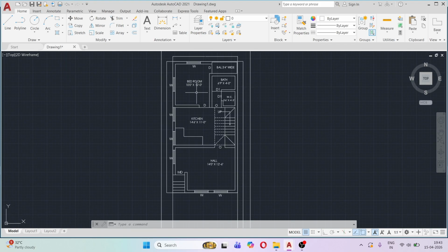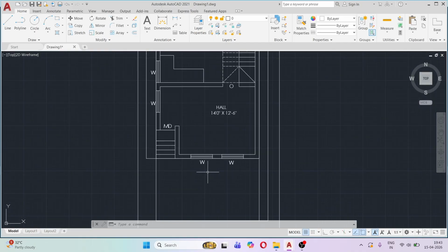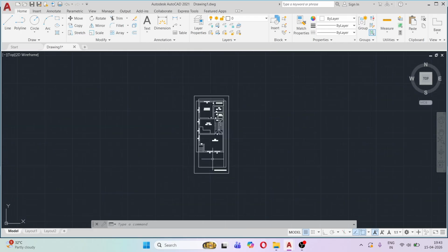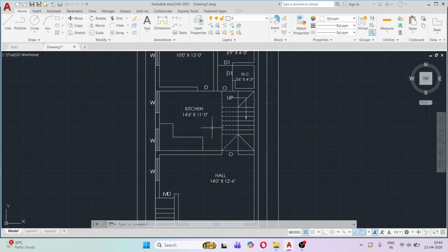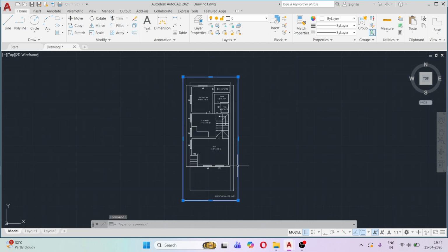or any structural design for a building, you will get the architectural plan. So here you can see we have one architectural plan. From this architectural plan, we have to convert it into a beam column framing layout. This is the first step, and then we can go to any software. Especially here we are going to see it in ETABS software. So how to prepare a beam column framing, I am going to teach you in this video.